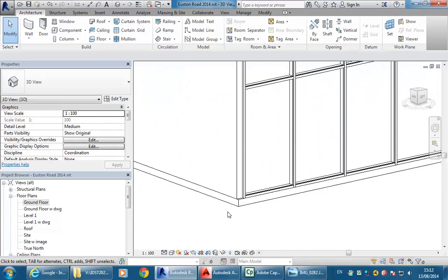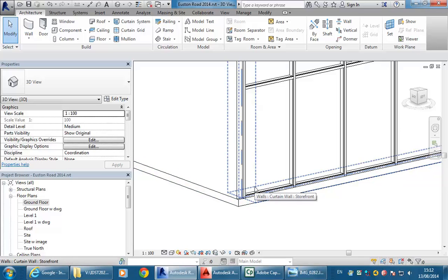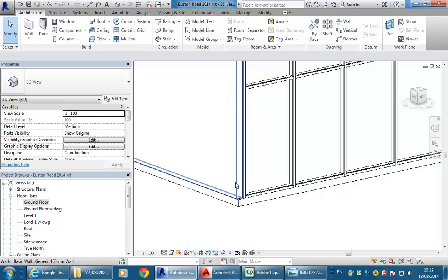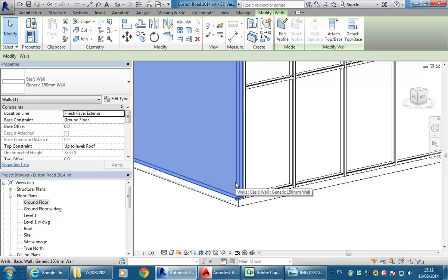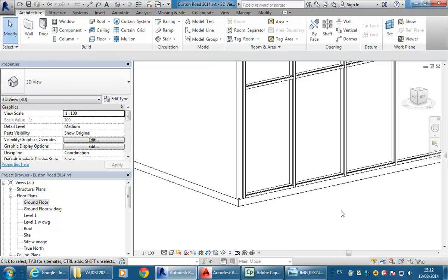Yeah, it's funny. Pick walls, and those different options can give you the floor edge in a funny place. When you've got different walls, it's even stranger. I'm still confused with interior and exterior, like where do you want it to mesh? Well, with ground floors, exterior face or interior face? Normally you want the bottom floor on the outside of your wall, no matter what. But when you're drawing an internal wall, it doesn't matter then. It's going to have a side, so move it to wherever you need it to. Yeah, exactly. That's right.